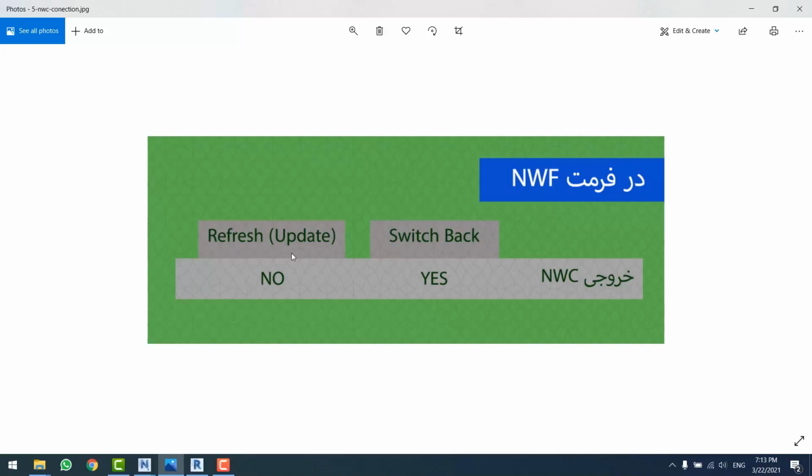Basically, while we are carrying out our project in Navis, we import our Revit file into Navis directly by click and drag, since if we export it as NWC type, we won't be able to refresh it. But as I mentioned before, in heavy projects, we are forced to export our file in NWC type, since if we import it directly, Navis would import the Revit file and also create the NWC file types simultaneously. In this process you may face difficulties.